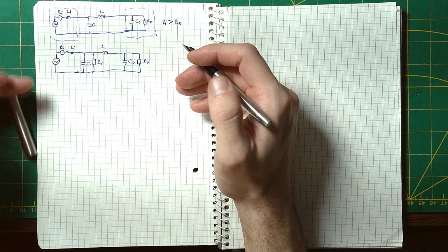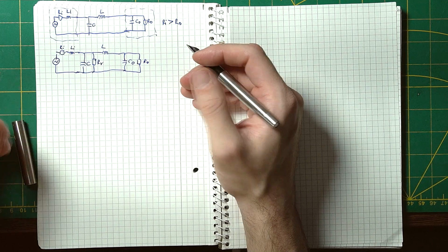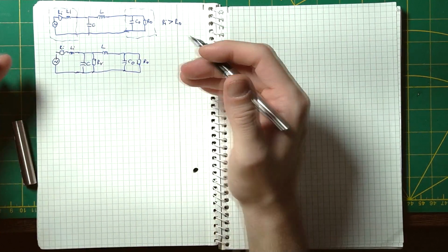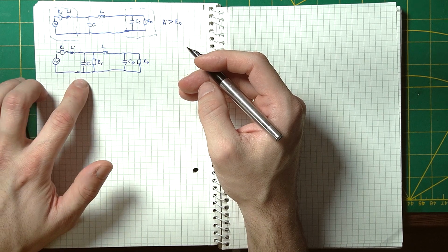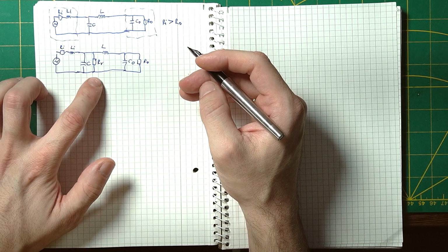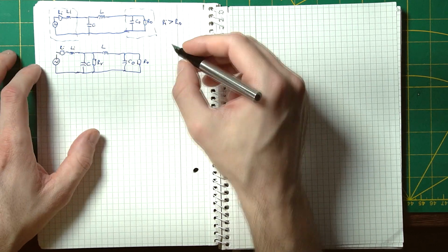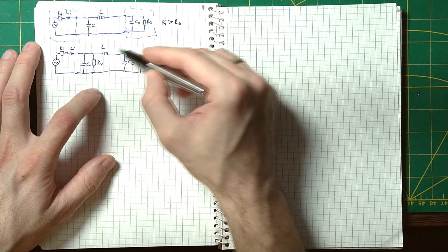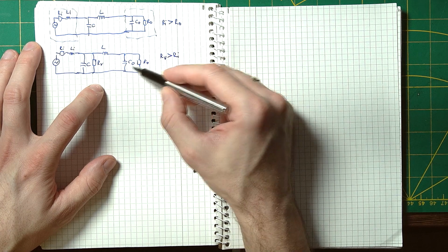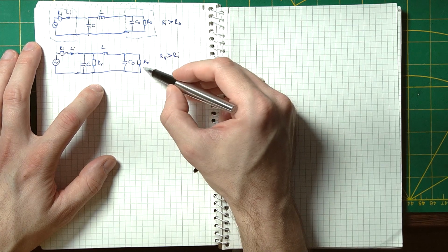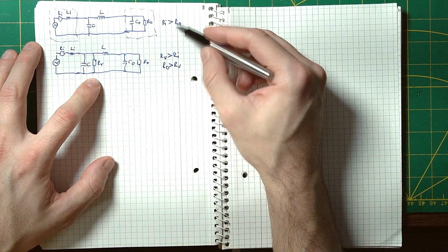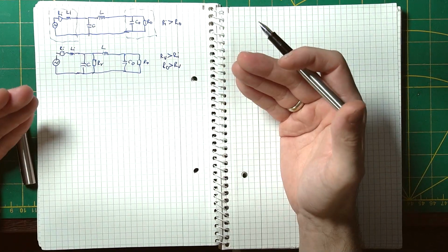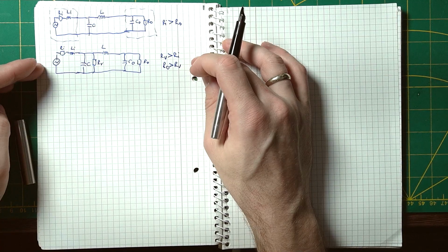We could try something like this where we have an intermediate virtual resistor, and to get this thing to work correctly, our virtual resistor, which is in parallel with the capacitor, should have a larger resistance value than our internal resistance. On the other side, our output resistance is in parallel with the capacitor, so this should be the largest of the two, and well, this isn't really possible. You can't get these three equations to work at the same time, so this is not a solution.